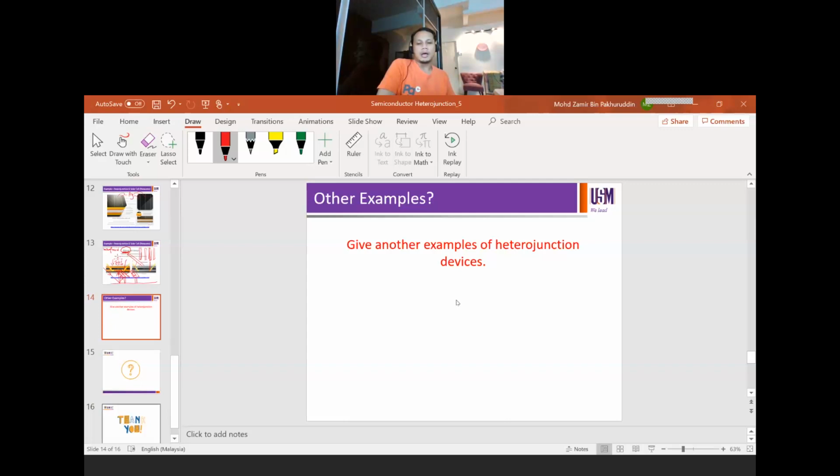So whenever you discuss heterojunction, make sure you know about lattice mismatch. What's the percentage like? How do you calculate it? What sort of materials normally go on other materials, right? Because you can't simply deposit any epitaxial layer on any substrate.